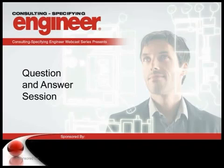Well, I guess under that condition, I would say that you're misapplying the transfer switch. Okay. Because your circuit is exposing that switch to a condition that it's not rated to handle, if I'm interpreting your condition correctly.